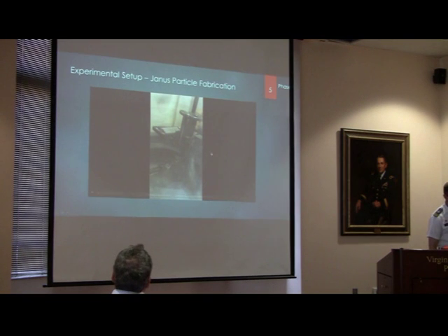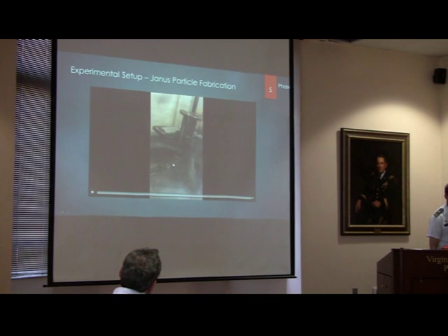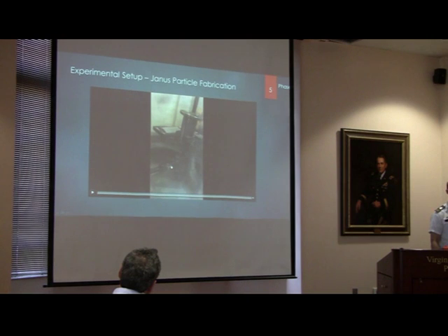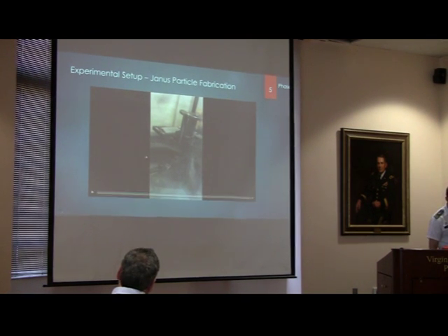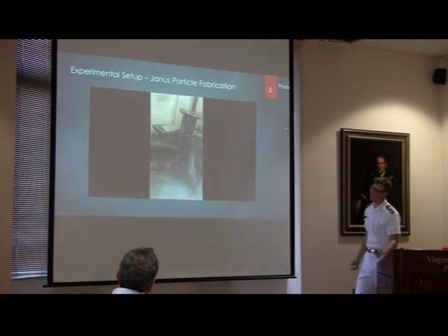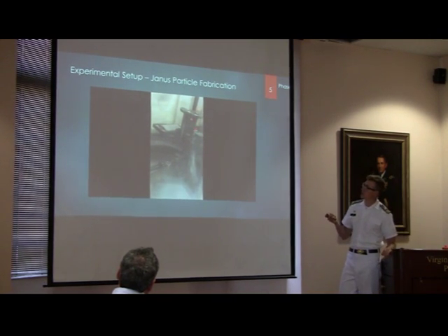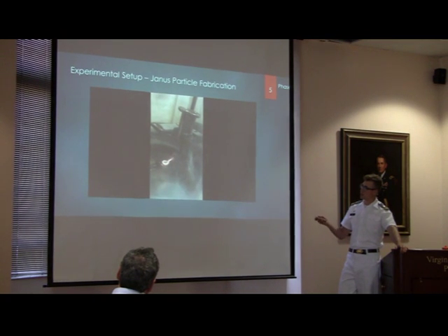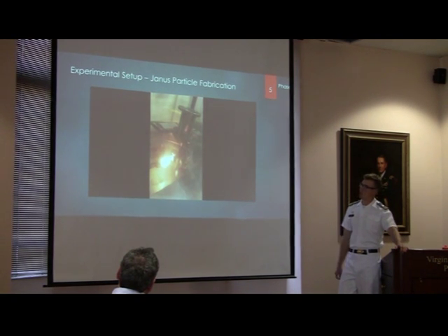It's a pretty fascinating process because you'll see as the pressure goes down, we'll start pumping a current through here, about 50 to 70 amps, which is quite a lot. 10 amps is enough to kill a person. This will go white hot and actually start to melt the metal. What you're seeing over here, this hand, is zeroing the thickness monitor. Right now it's 0, and it'll tell us what the thickness actually is. You can see the current pumping through this small wire basket, and it'll get so hot that it evaporates the nickel onto the actual particle.